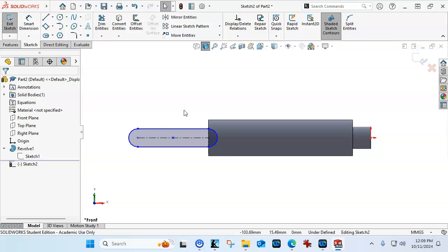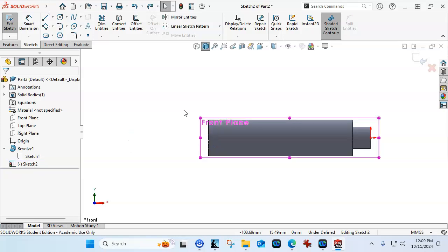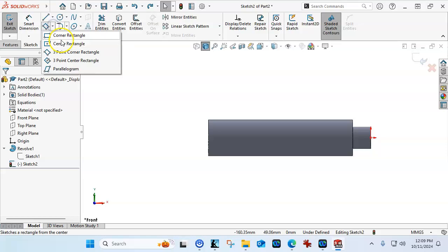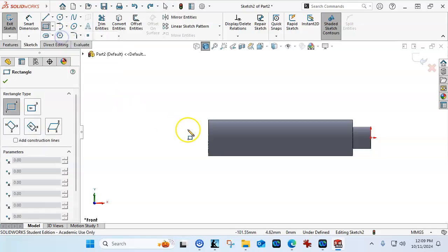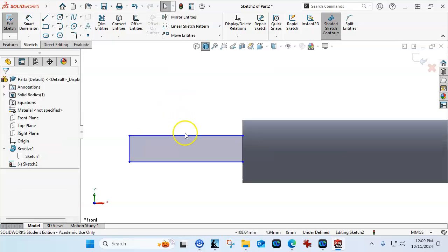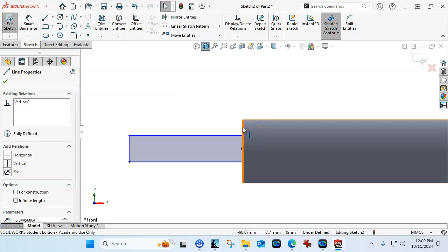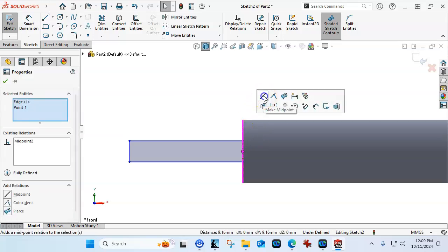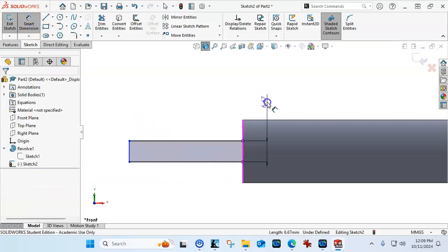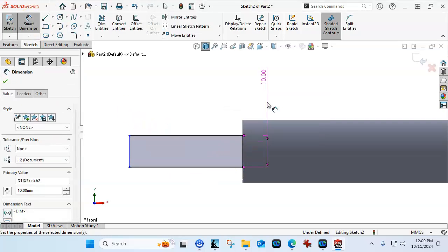The other technique, since there are always going to be alternatives, is that if I go with a corner rectangle, I'm looking for that to be in place, and I would like to select the midpoint. I'm looking for that end, and I'm going to make it the end point. So the thickness on this, the radius is 5, so that's going to give me 10 for the width.